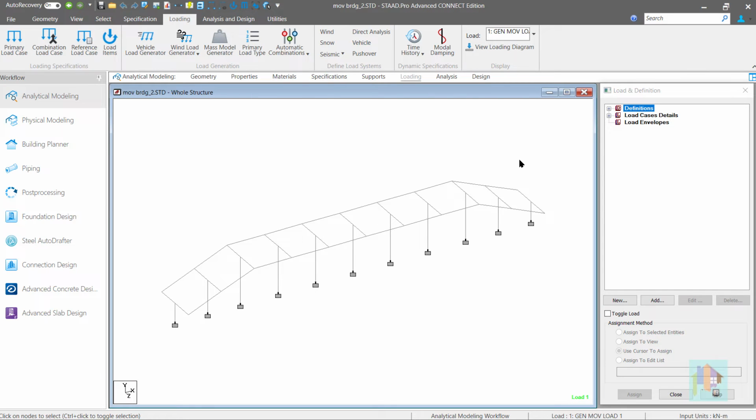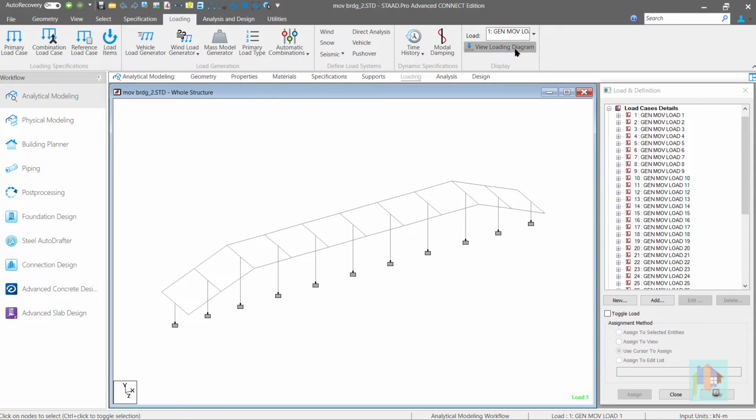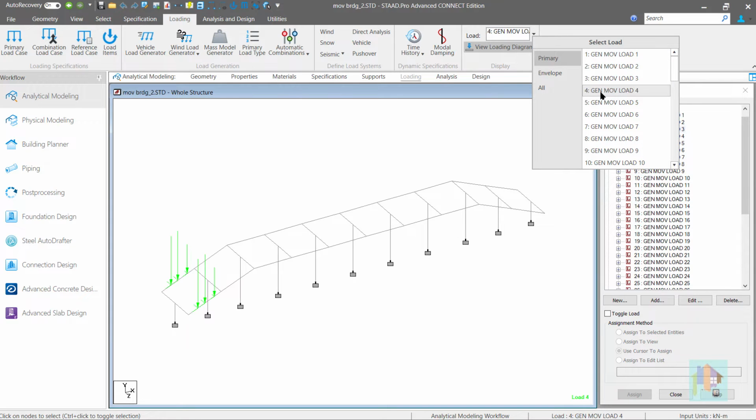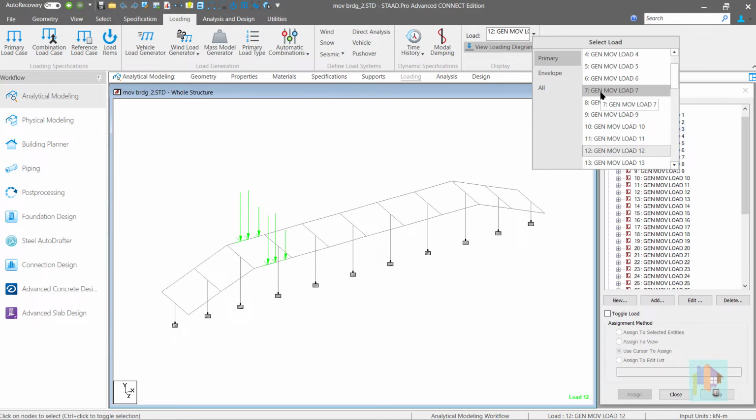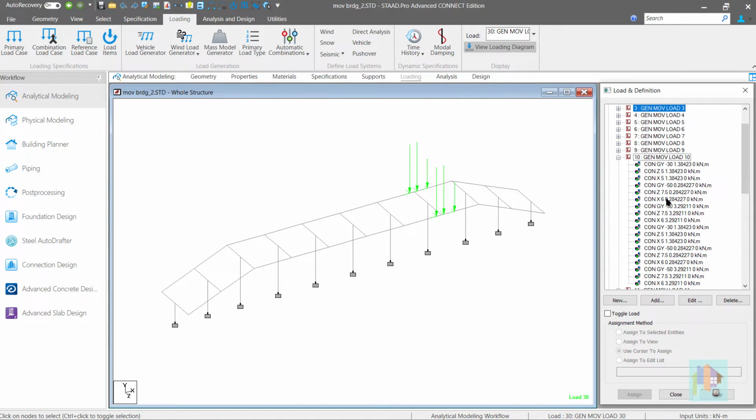How is the structure affected when the load position changes? Consider this simple frame structure with multiple bays. Load from 3 wheels with different axle loads is applied on this frame. Multiple load cases are generated to capture the movement of the load from one end to the other end of the entire bay. These loads are generated using a custom tool. I will discuss this later. For now, check the bending profile of this girder.